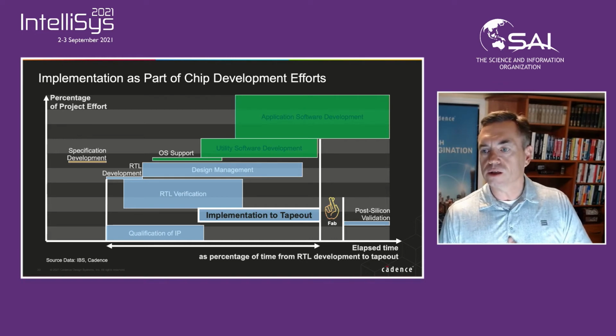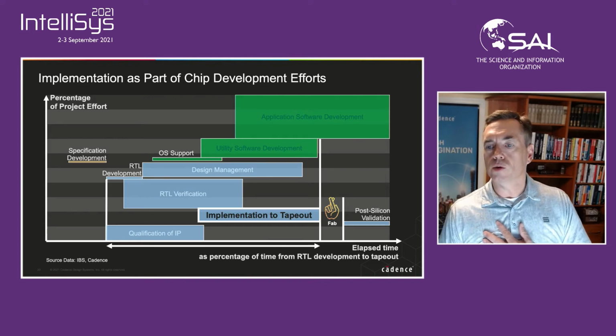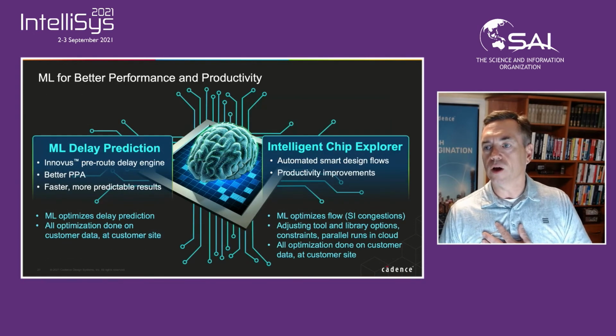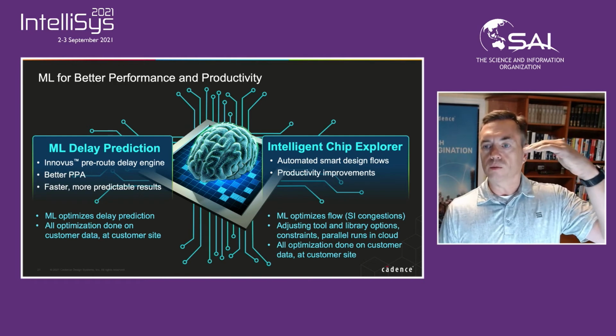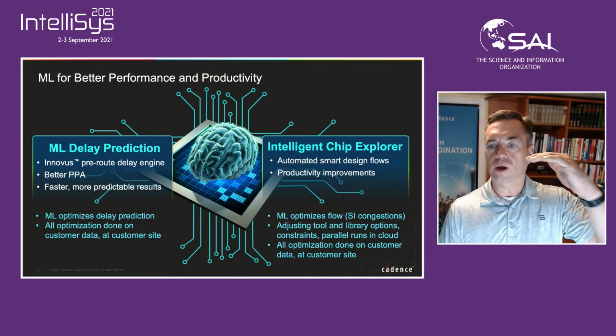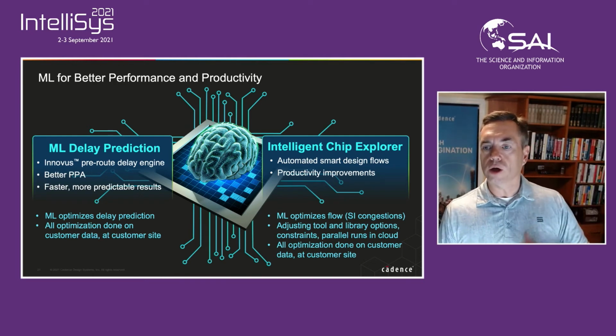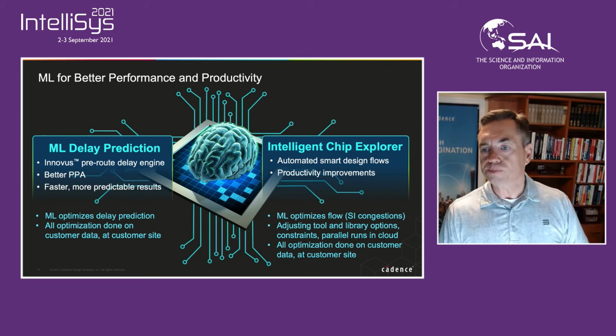There's this very large spot in the center where you do the implementation of the environment and the implementation of the chip. And that's where you go, in a digital world, from a description language like Verilog to the layout and then the GDS2, with the different phases like the gate level in between. And there are really two pieces here.